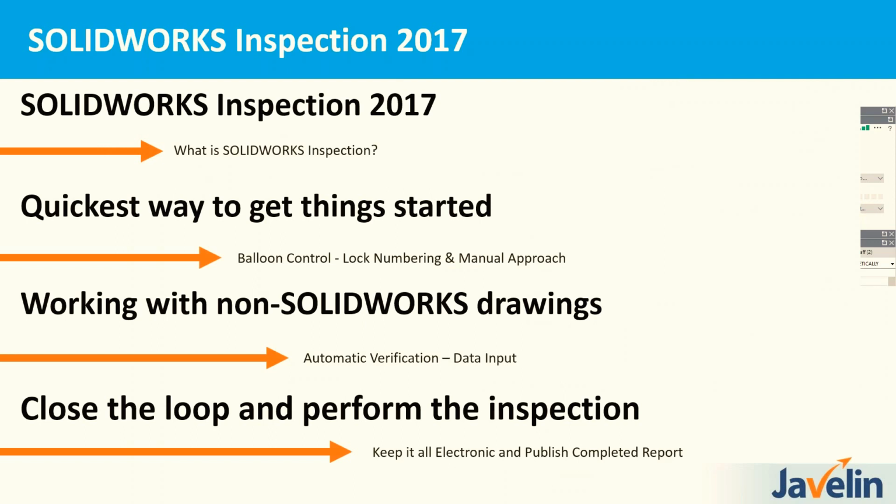So that's the general overview of inspection and how we can go from starting off with our models, going through our drawings, and then if you want to use the add-in inside SOLIDWORKS, you can do that, or you can export that to the SOLIDWORKS inspection project, and that's all streamlined. You can do that right away, and everything can get placed in no time at all, rather than doing everything manually. Inspection can be a great help in that area.